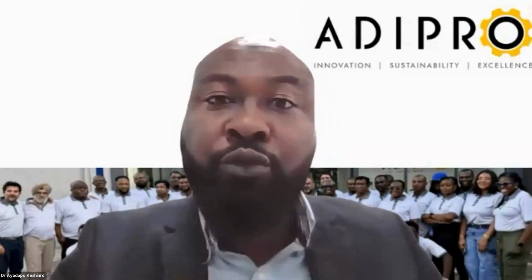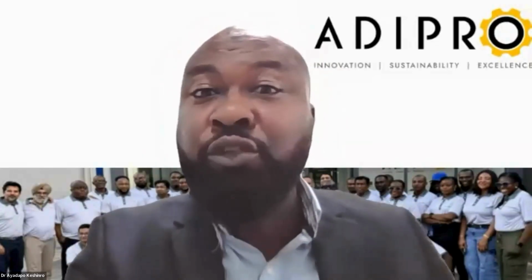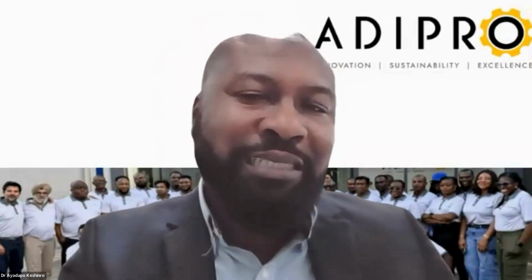We are not in the ultra-low sulfur fuel area yet, so most of our fuel has high sulfur. Our testing is done with that in mind. There's one more thing I need to say. A lot of the vehicles in Africa are not brand new. They have already been used before being shipped to Africa, so the engine is coming in with a lot of wear to begin with. Traditionally, a lot of the additives on the market today do not consider that for the African market. When you're buying an additive, the manufacturer is assuming that those API-rated additives were made for brand new engines, because they are tested with brand new engines.